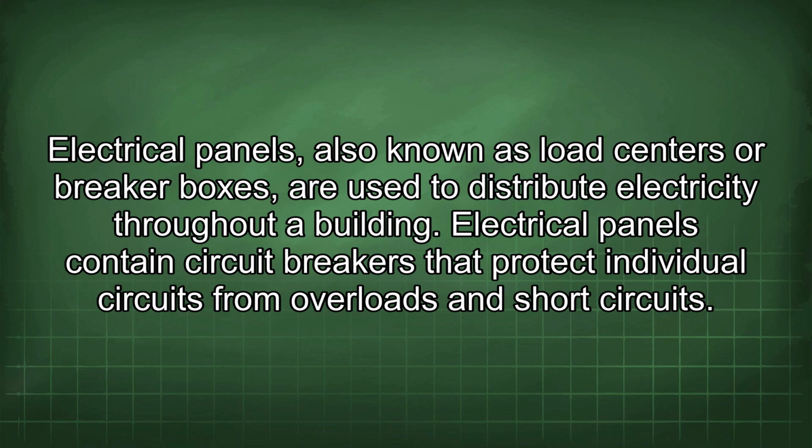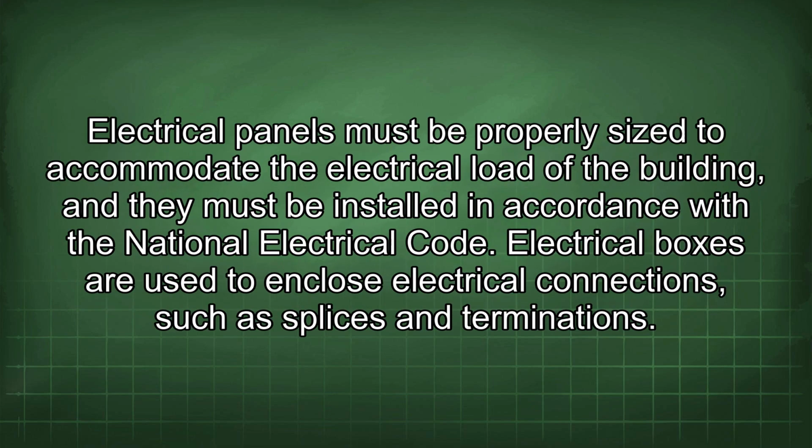Electrical panels, also known as load centers or breaker boxes, are used to distribute electricity throughout a building. Electrical panels contain circuit breakers that protect individual circuits from overloads and short circuits. Electrical panels must be properly sized to accommodate the electrical load of the building, and they must be installed in accordance with the National Electrical Code.